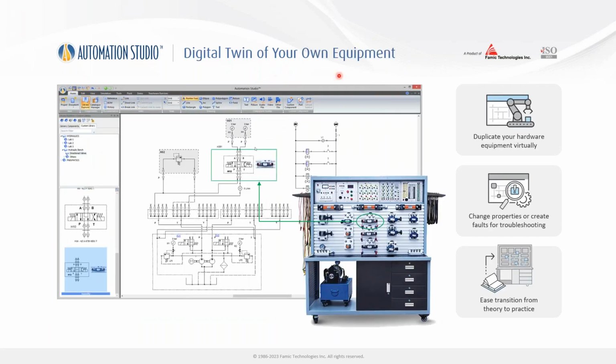You can also create a digital twin of your own equipment. For example, you can see the hardware kit and the circuit. On the hardware kit, you can see the similar circuit we have drawn in Automation Studio, and we have linked this circuit with the circuit on the hardware kit, right? With the help of OPC server client. So with the help of this, you can get real-time feedback of the actual hardware kit through Automation Studio, right? So in this way, you can create the digital twin of your own equipment.